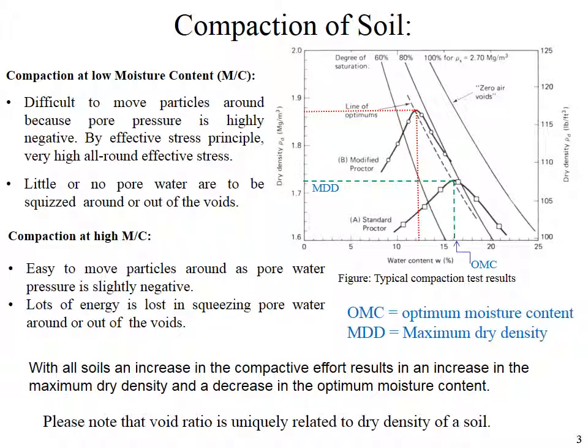Compaction at low moisture content. Difficult to move particles around because pore pressure is highly negative. By effective stress principle, very high all-round effective stress. Little or no pore water is to be squeezed around or out of the voids.